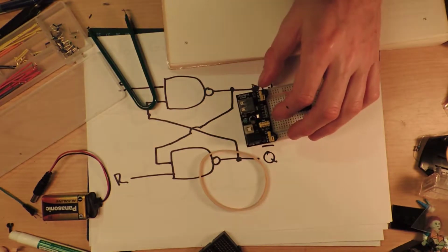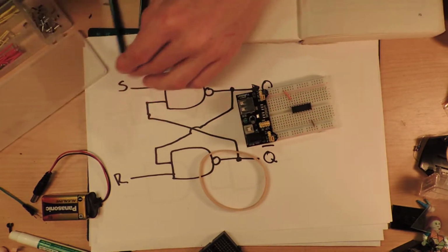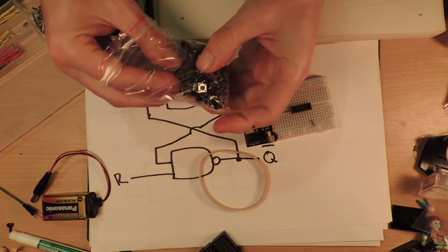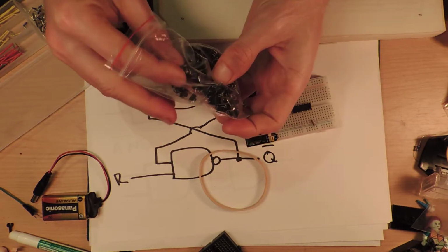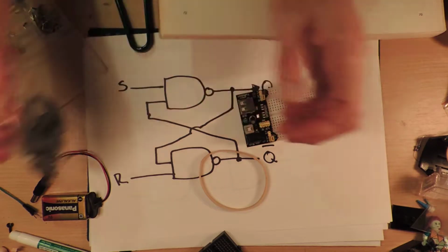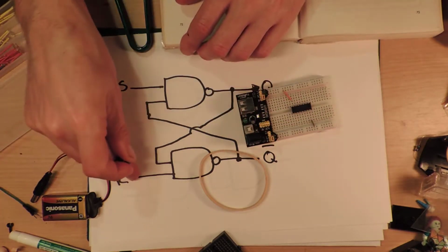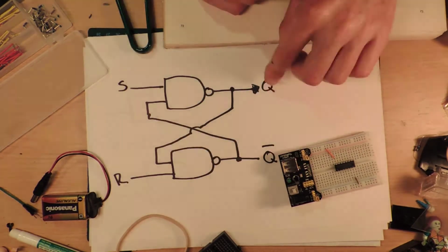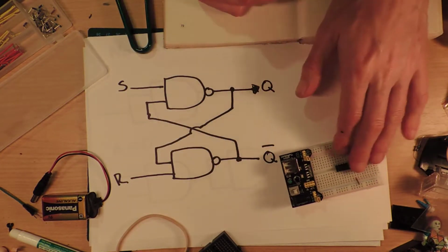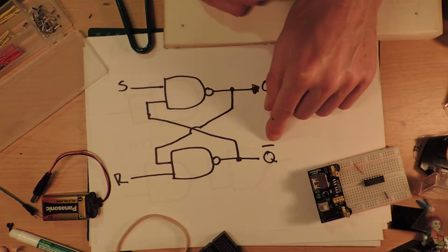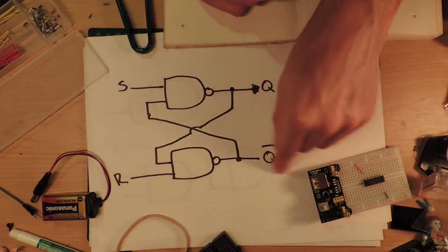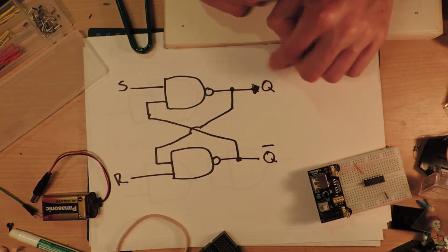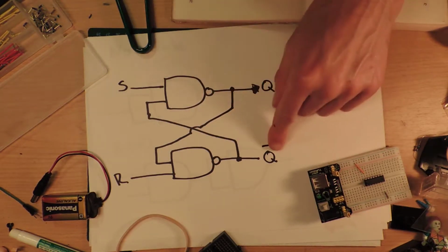So the first thing I'm going to do though is these two inputs are going to come via, so the way that this thing works, as you'll see, if this is a positive voltage, that will reset the circuit, so this will go high and that will go low. This is the output. The little line over the top means that it's true when it's low as opposed to being true when it's high. I guess that's how you can look at it.